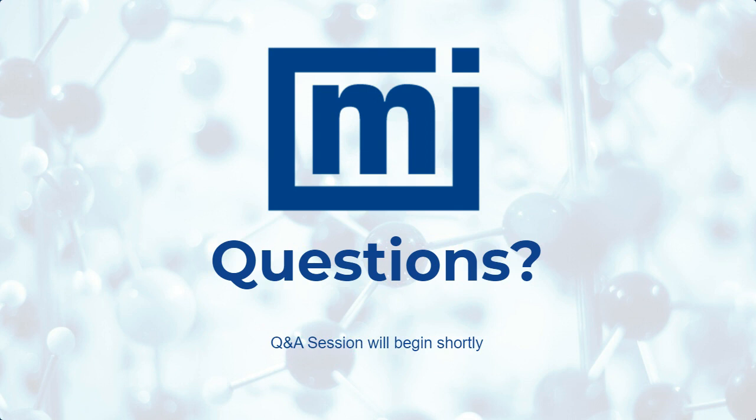So with the FT4, as it comes out of the box, you can test with oxygen and you can test with nitrogen, the various range of tests we can do with that. However, I think if you wanted to use something like argon or some other gas, really that's going to be coming down to how you can store your powders. So again, if you're using a desiccator to create your environment, you're going to need to be able to do that with that particular gas. Obviously, then you're going to have to think about preventing that gas from escaping, etc. But there's no fundamental reason why you shouldn't be able to do those tests. And again, I'd expect the same kind of results from that kind of testing.